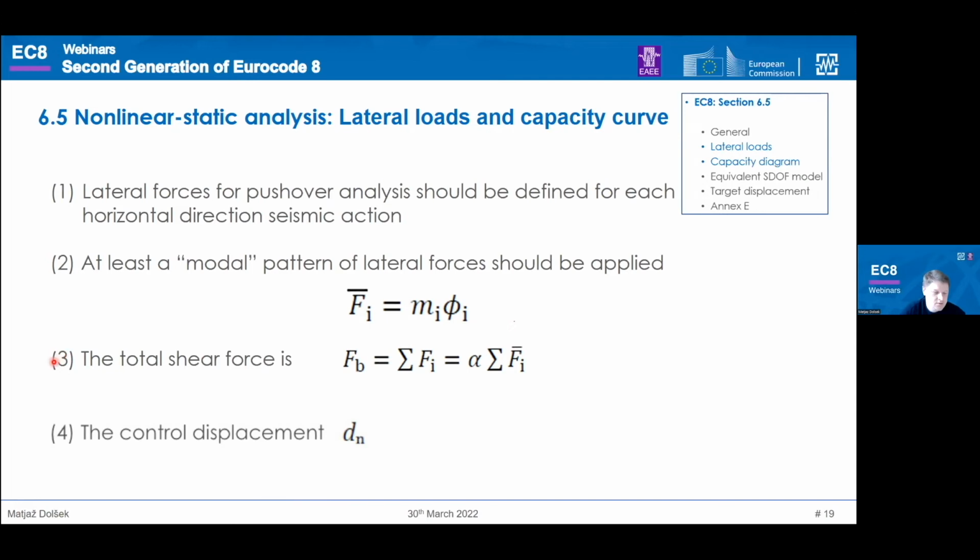And there is also the definition of how to calculate the total shear force, of course the sum of the lateral forces, with alpha times the sum of these forces. It is actually prescribed that the shape of the lateral forces should be constant, which means that there is no prescription of any adaptive methods to be used.